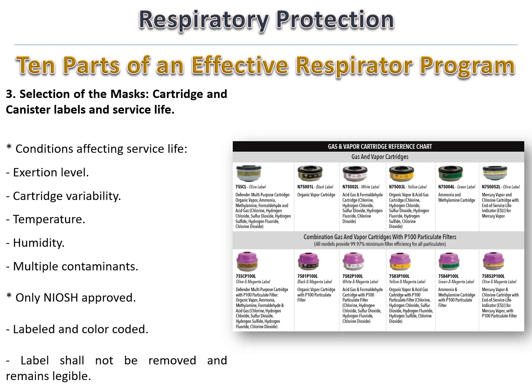3. Selection of the masks, cartridge and canister labels and service life. Conditions affecting service life: exertion level, cartridge variability, temperature, humidity, multiple contaminants. Only NIOSH approved. Labeled and color-coded. Label shall not be removed and remains legible.